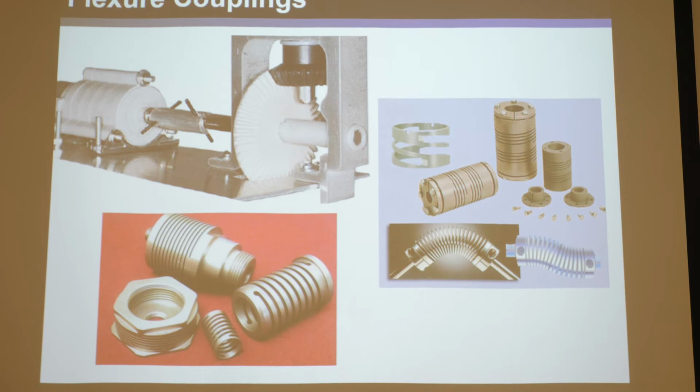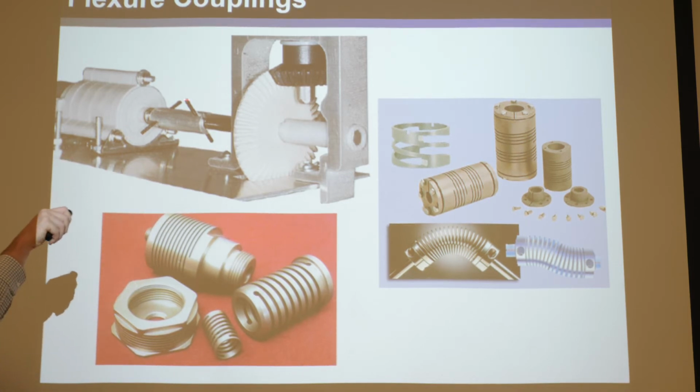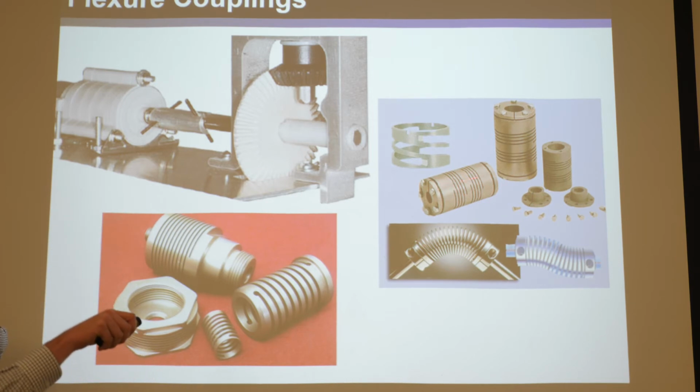So what people do is here's a rigid coupling. You ground the motor, you ground the shaft on the other side, and then you have a cylinder here, and you cut slots in it, and you put a peg through this shaft and a peg through that shaft, and then there's some slop in there, and so it can accommodate the misalignment, and all it will pass through is the torque, and all the rest will be taken up in the slop. The problem is they clatter around, which generates friction, which makes them inefficient. It's nicer if you can just use a flexure coupling, a single piece that can deform to join the two directly. A single piece, no clatter, no rubbing or friction, and can still pass the moment while accommodating imperfection.